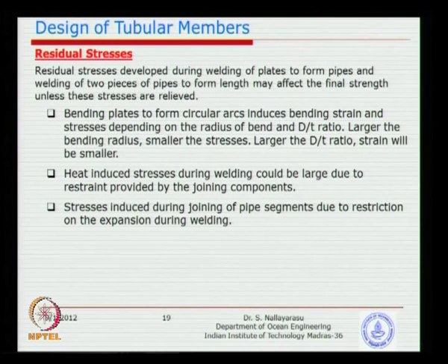The residual stresses are basically a cause of worry, because you have no control during the process of design. As a designer, you don't have control. So what we need to do is create a procedure in such a way that you do this as part of the design process. Make a specification, give it to the fabricator that you should only follow these steps, so that my design becomes valid, because if you do something else, the design is violated, because the residual stresses created are higher than what I have permitted.